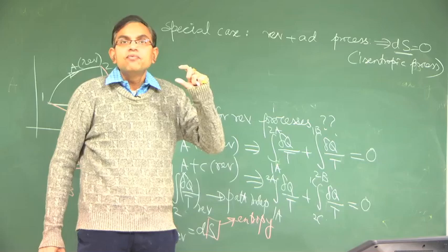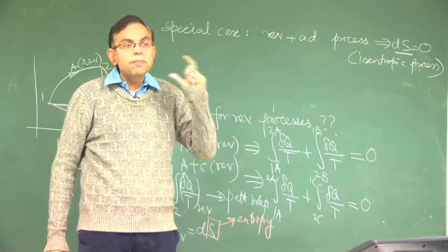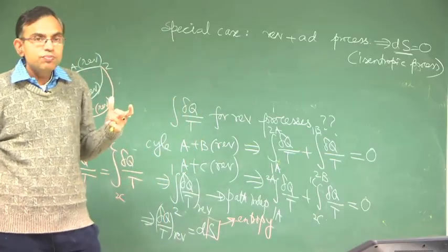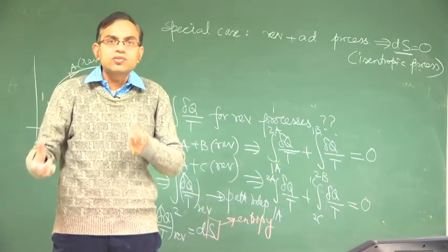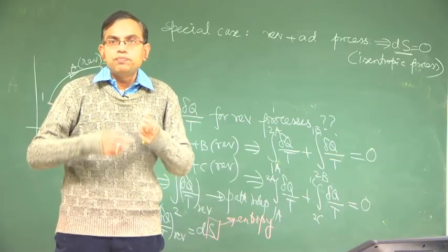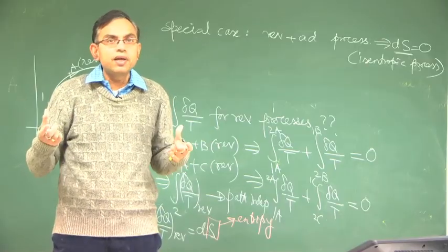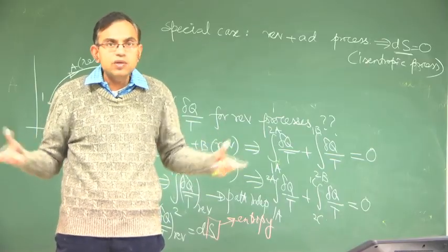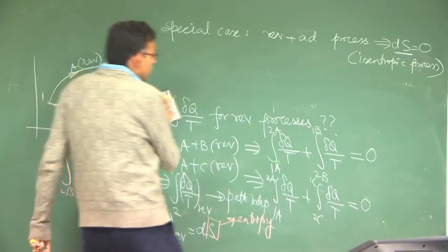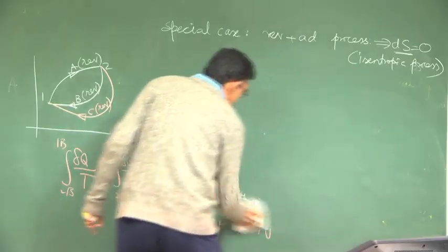So it is very convenient if we can draw the Carnot cycle in a temperature entropy diagram, or TS diagram, and that is how, because we want to compare all the cycles with the Carnot cycle, the drawing of cycle diagrams in the TS plane has become so popular. So I am just giving you the genesis of why we draw TS diagrams. So we will try to draw the TS diagram of a Carnot cycle.